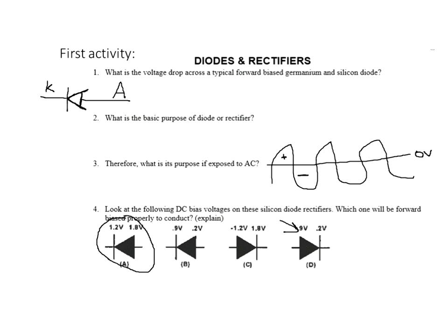No. We know that diodes will conduct, some of them, even with 0.5 or 0.6 on it. So which one will be properly forward biased? The only possible one that's forward biased is A.